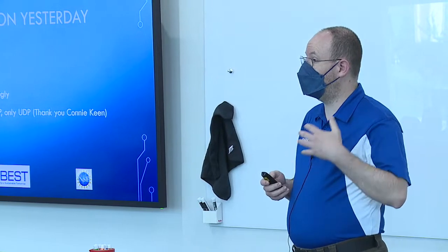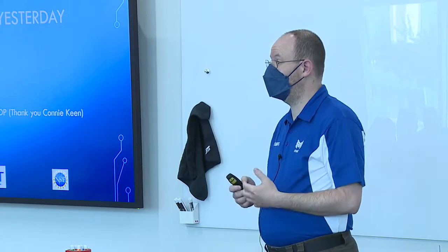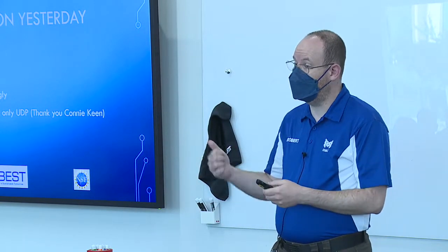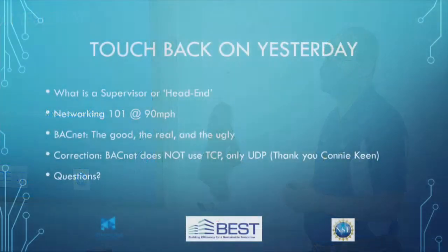They've added a lot of bells and whistles. Not that it always gets used, but at a basic level, your supervisor needs the ability to do alarms, histories, user interfaces, and help facilitate communication between your controllers if they don't have a built-in way to do that, which some systems do and some don't.